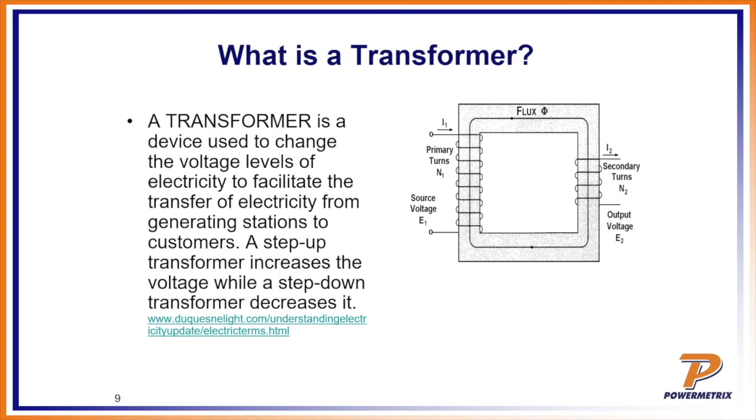So a transformer really is a device that changes the amount of electricity, usually a voltage or a current, down to a safe application. As the primary current or primary voltage comes in, a magnetic field is used to step that current down. And a good thing about a transformer is that it's a great form of isolation between the primary and secondary, allowing safe operation for the technician.